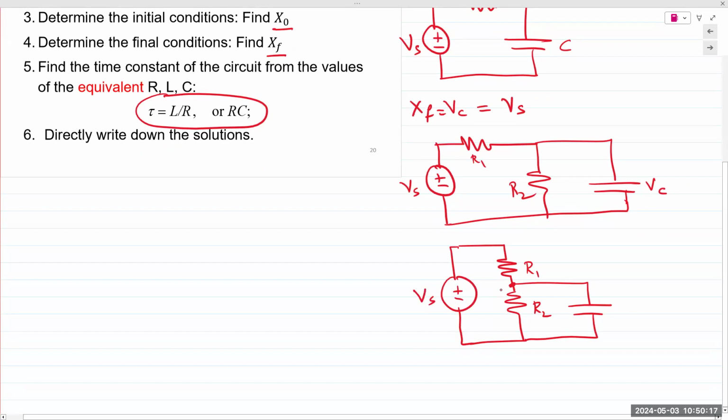If you remove the capacitor, you know that the 2 resistors are in series. So you have some voltage across R1, you have some voltage across R2, which would eventually be the case when C reaches full charge, because it behaves like an open circuit. But the capacitor voltage in parallel with the R2 resistor will remain exactly the same. But that voltage is not equal to Vs. So you have to find the equivalent circuit by removing the capacitor and analyzing between those open terminals.